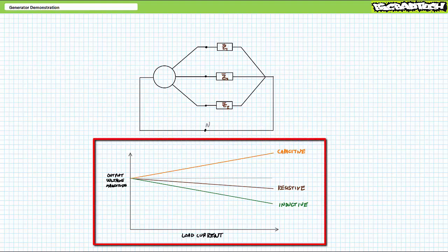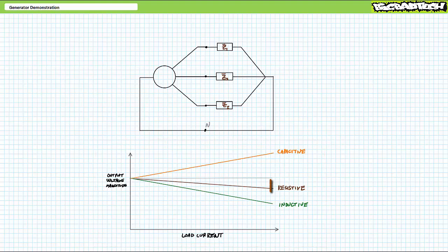If you recall, this collection of curves illustrates the voltage magnitude regulation characteristics for a synchronous generator with a range of load conditions. Viewers will note that resistive loads experience reduction in output voltage magnitude as current demand increases. Inductive loads experience a similar reduction effect, only more pronounced. Capacitive loads, in contrast, experience increased voltage magnitude as current demand increases. Additionally, we learn an operator can compensate for these undesirable changes in voltage magnitude by increasing or decreasing field current to return voltage magnitude to a desired specification.